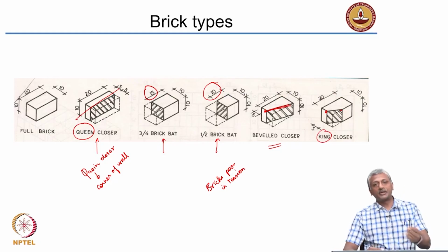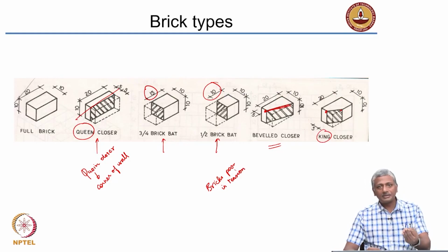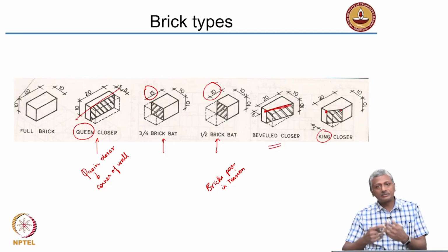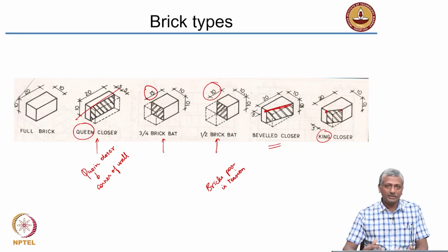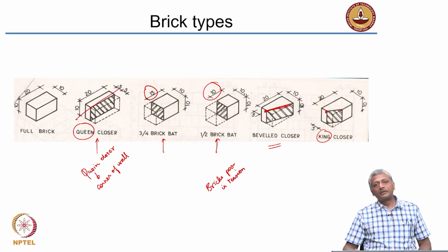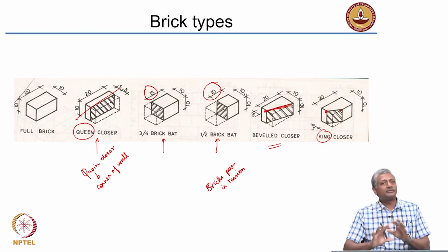Most construction materials, brick, stone, concrete, everything, all these materials are very strong in compression but poor in tension. Steel, of course, is as strong in compression as it is in tension. One material that is opposite that is wood, which is a lot more stronger in tension, especially when you are going along the grains of the fibers that are there in the wood, okay, as opposed to compression. So, wood is stronger in tension than in compression. Right. So, different materials have different types of attributes, you need to use them correctly.